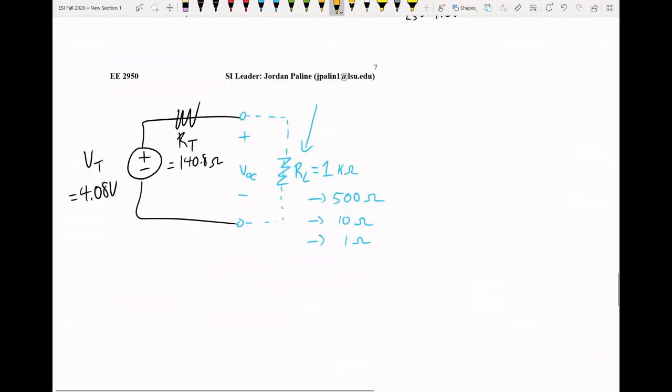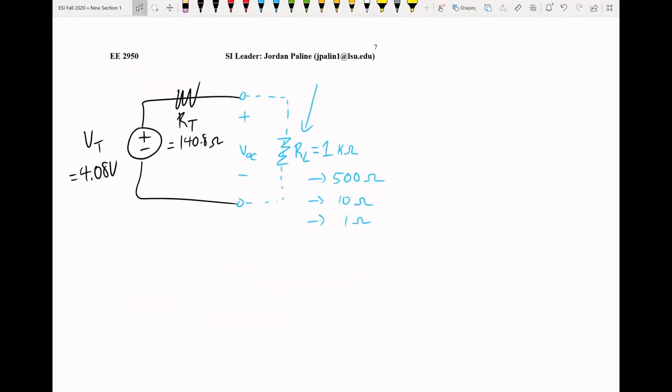So the Thevenin and Norton circuits basically say that, you know what, I don't want to keep doing that analysis over again. Let me just create a simplified circuit so that if I want to change the load resistance, I only have to do one step of work to find the new value. So now I only have to do one line of algebra to figure out what the current or the voltage is through it. And so it can be a very powerful tool when applied in the correct scenarios.